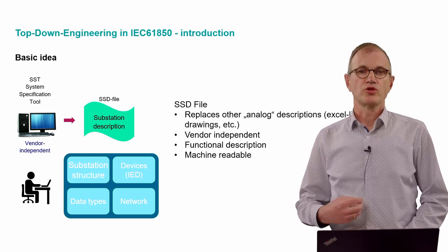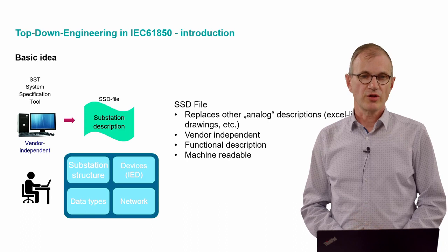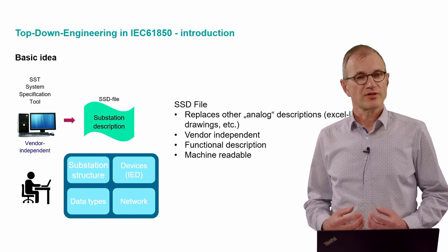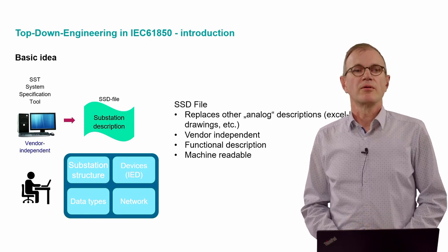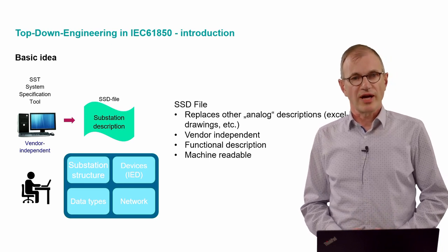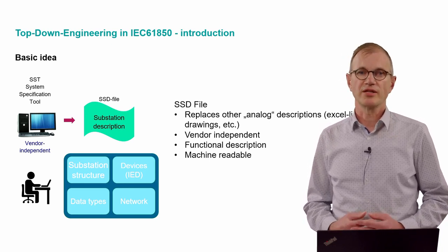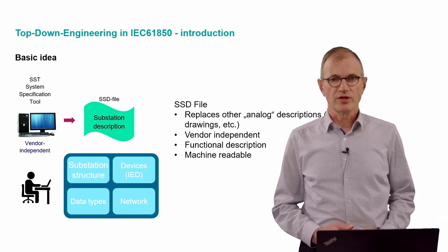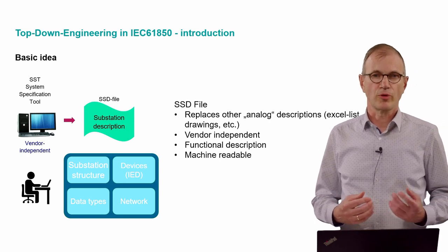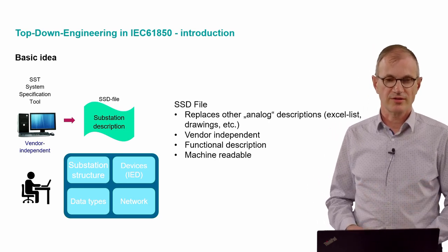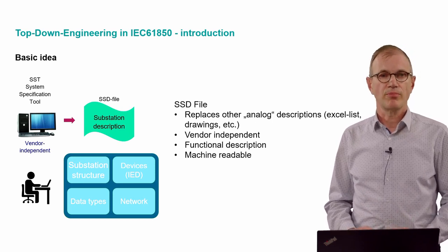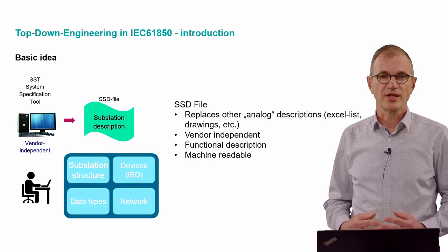Such a tool is vendor independent. So the sense of this is that you do not fix a vendor like Siemens. You just describe your requirements, quite neutral. This file, the outcome of such a tool, replaces other analog descriptions. For example, Excel lists with signals, drawings with topology, or even Word files which describe which protection functionality you need. All this can be part of this SSD file in a standardized way.